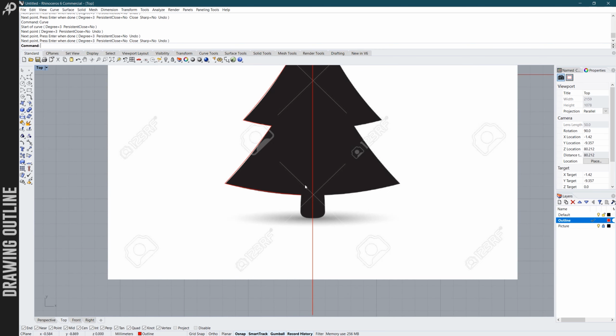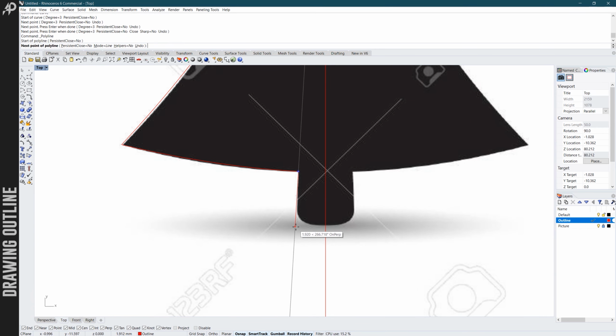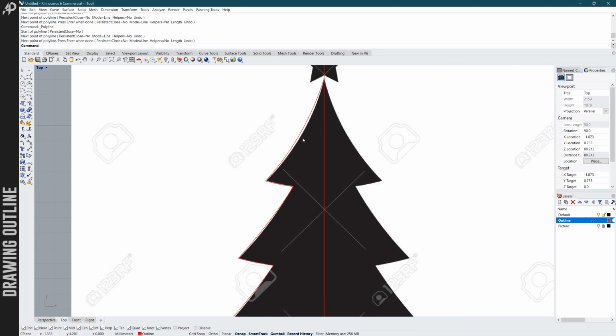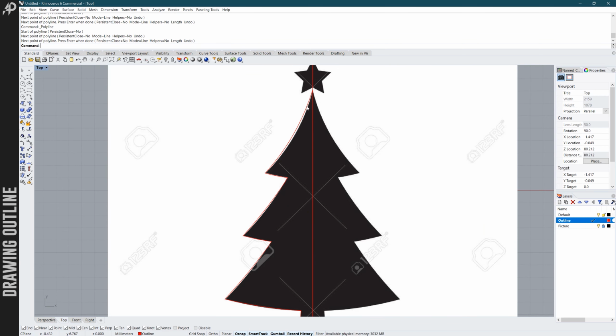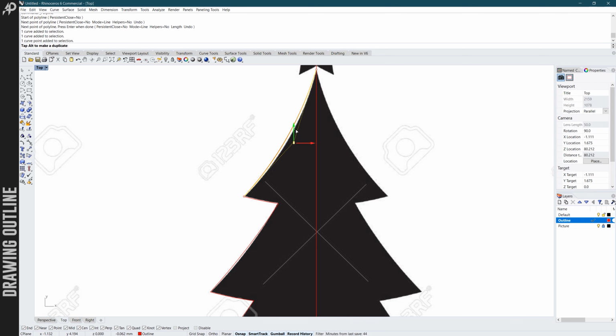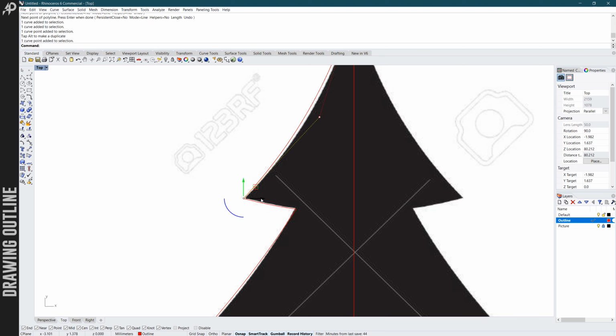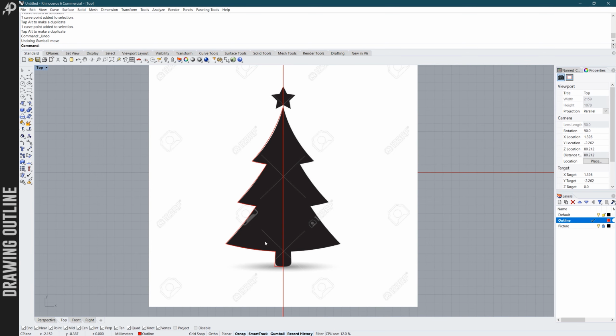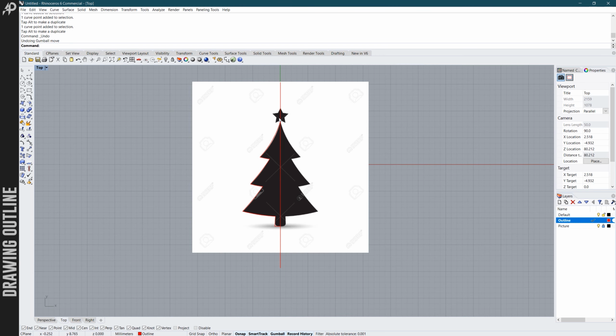Okay, now I want my lines to be straight, so I will choose the polyline command again. Draw one line, draw the other one. And I can see that I didn't really fit to my sample object, so I want to edit my curves a bit. I can either click it and edit my control point, but I will be in trouble when I get to the corner, because I have only chosen one control point and there are two control points on top of one another. So a lot better way to edit curves is to just select all the curves.